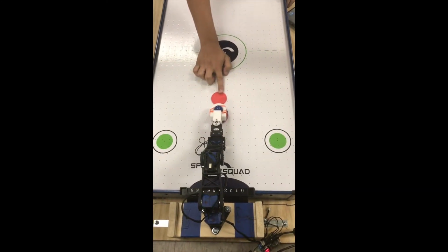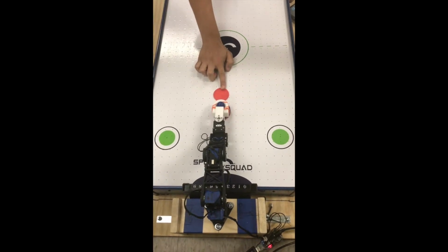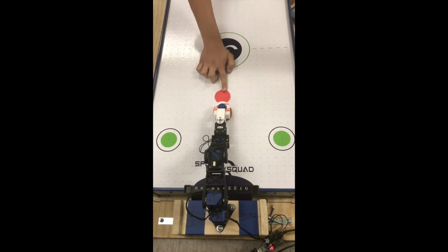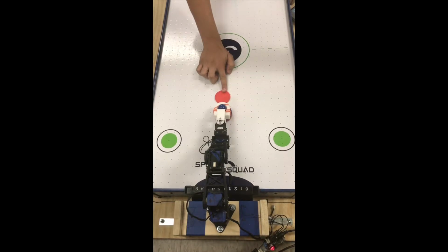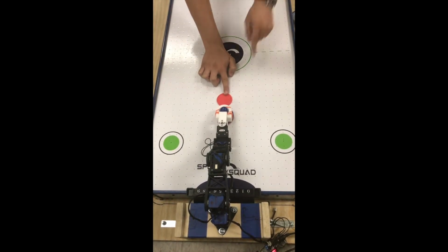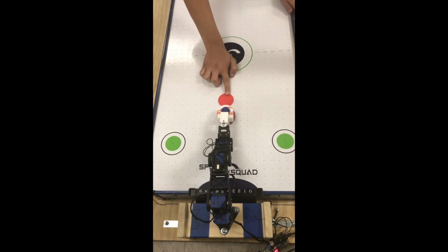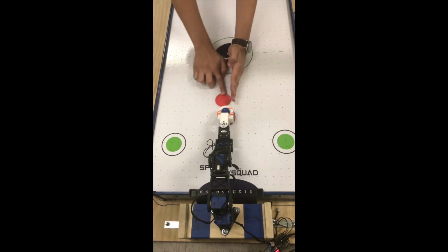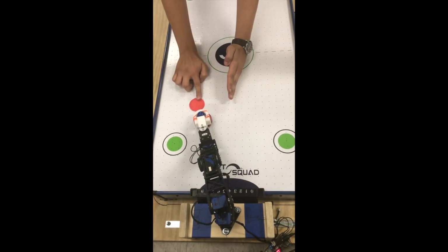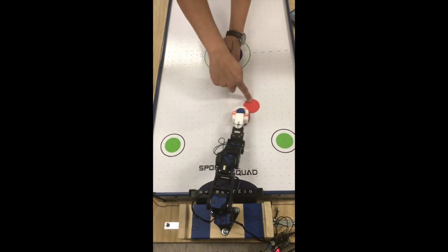We implemented both forward and inverse kinematics for the Rex arm. Forward kinematics methods were mainly used for testing and debugging purposes. Inverse kinematics played a much more critical role in the project. We used the XY coordinates of the puck in the robot's reference frame to constantly calculate the puck's angular offset from the vertical axis. This allows the Rex arm to follow the puck at all times.